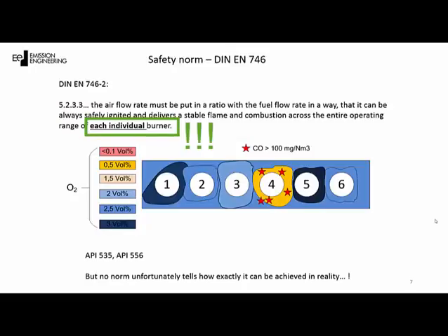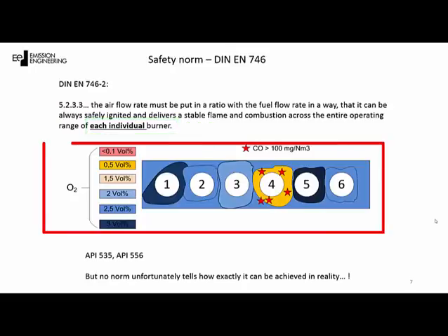Take a look at the oxygen concentration profiles on this slide. How do you think this requirement can be fulfilled in a multiple burner system with only one oxygen analyzer that is not necessarily measuring on a representative basis, nor taking tramp air ingress into consideration?